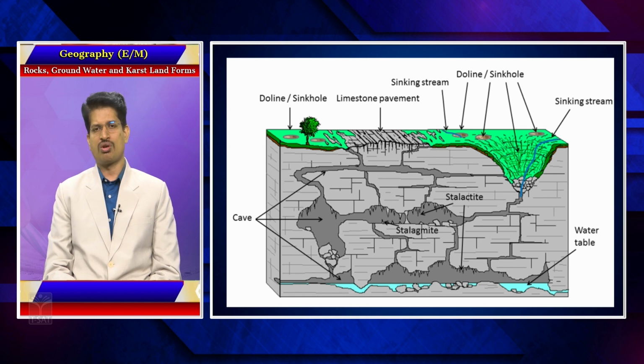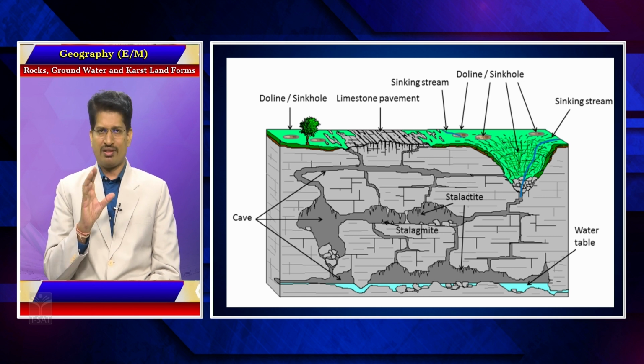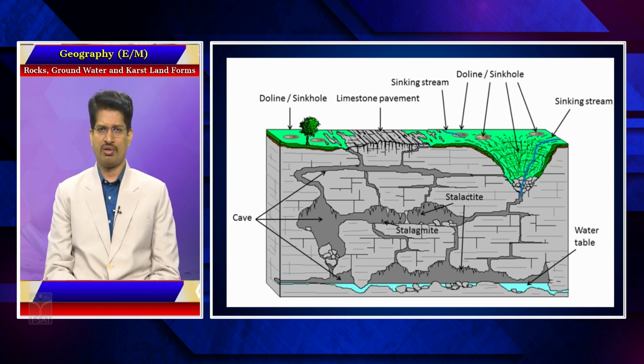Because this rock itself is made up of limestone and dolomite, which has a solutional nature, dissolving in the water, as the sinkhole structure is formed on the surface, different structures are formed in the interior of this rock because of the solutional activity, known as chambers and caves.